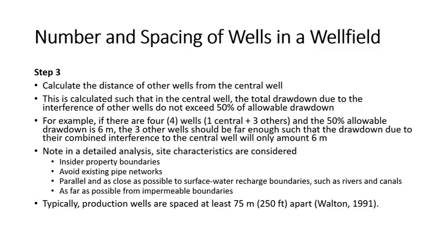Then we should design the three other wells so that they are far enough that their interference drawdown exerted on the central well will total to just 6 meters.